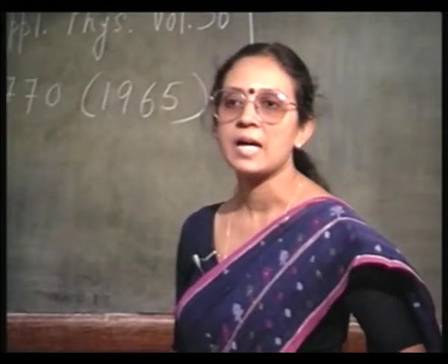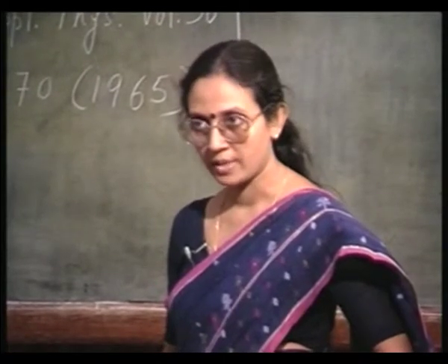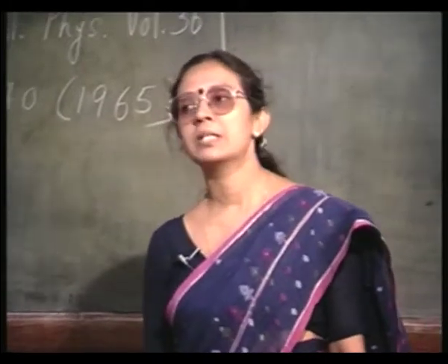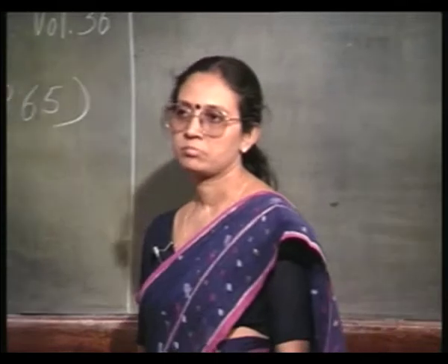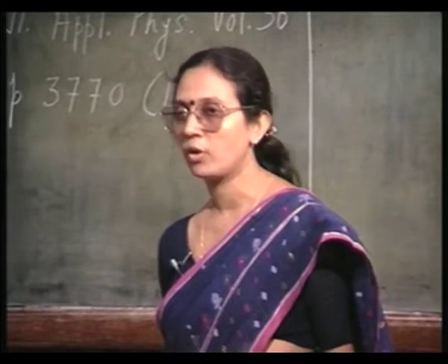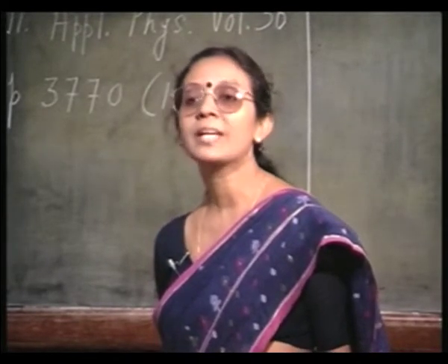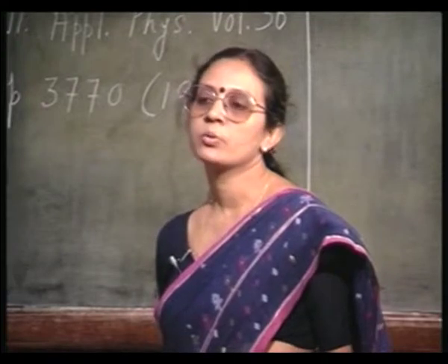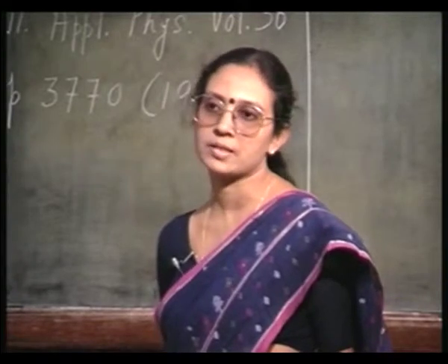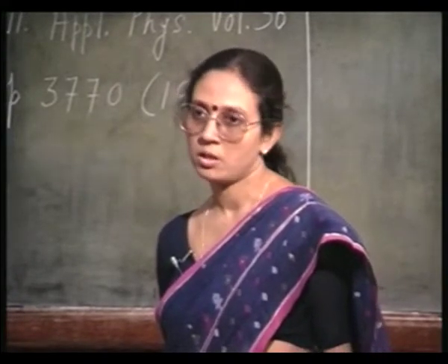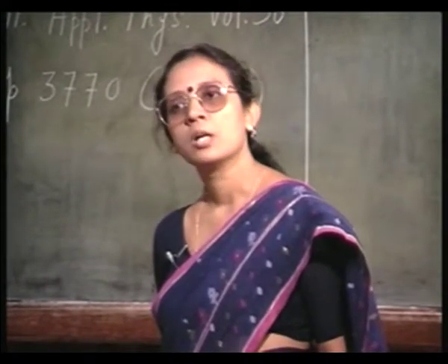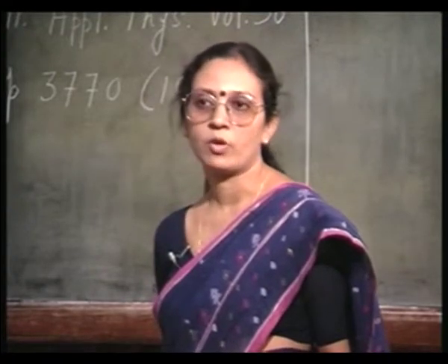Now, silicon has a great affinity for oxygen. It is very simple to oxidize silicon. This oxidation can be done in various methods, that is, if you boil silicon in nitric acid for example, you will form an oxide layer. This is called chemical oxidation. If you use silicon in an electrolytic bath, use silicon as anode and a noble metal as cathode in an electrolytic solution, apply a voltage between the two electrodes, then also a layer of oxide will form on silicon,